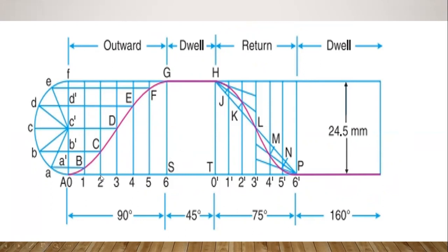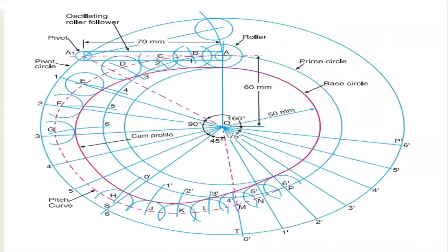In a similar way, take 2C, 3D, 4E, 5F and 6G as lengths and draw the arcs from there, cutting those arcs, that is from A to B. And by these points you have to draw the circles like this.